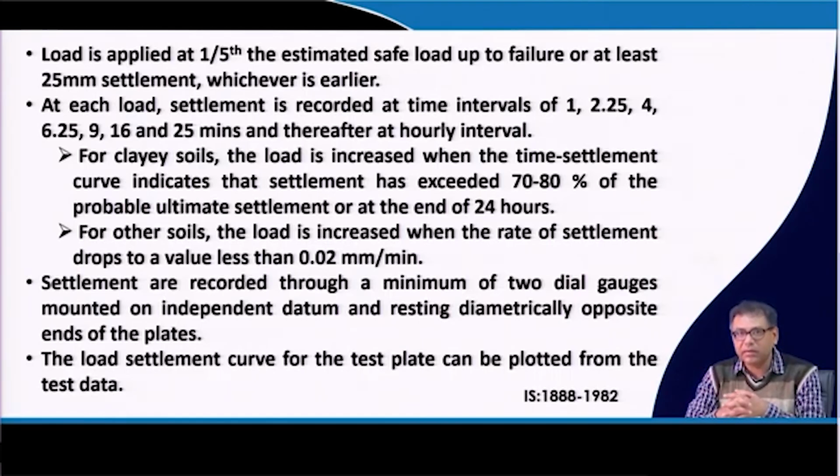This test is short term. So, that is why you have to go for 24 hours. There may be a possibility that the 70 to 80% settlement may not be achieved in 24 hours, but we have to go for 24 hours at least, then we will apply the next increment.